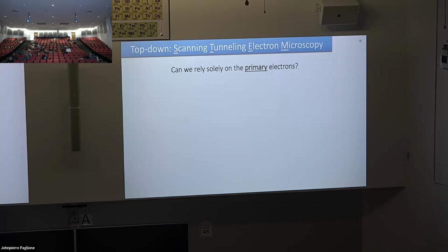Do you want that to be the case, or do you only want the holes in graphene and the substrate is more of a side effect? If you're doing the approach where you are removing atoms, so etching the graphene, you really only care about the graphene missing holes. It's not necessarily bad that you're etching the surroundings, but it's not the main intent. So if you didn't have to, that would be fine. But you cannot avoid it, right? You cannot control the E-beam to only etch one atomic thing.